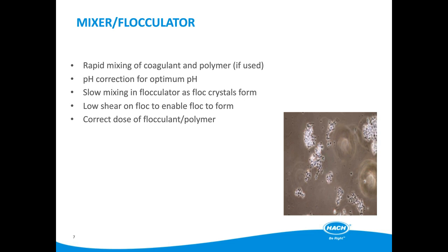Due to the low residence times in the modern DAF tank, the ideal floc is described as a pin floc. As the name suggests, the floc particles are small, making them more robust than larger flocs. For small flocs, the bubble size also has to be as small as possible, as large bubbles rise faster and would break the floc, but more on that later.